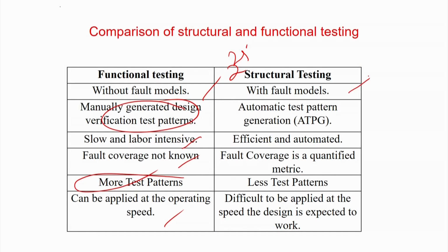Structural testing is with fault models, you can always apply algorithms to generate the test patterns, because we need not at all look at the functionality of the circuit, just the structure of the circuit is there. Stuck-at fault model is there, you have to find out which test patterns can verify that none of the faults are there. Today we will also see some of the ATPG kind of algorithms. Efficient and automated, fault coverage is a quantified metric.